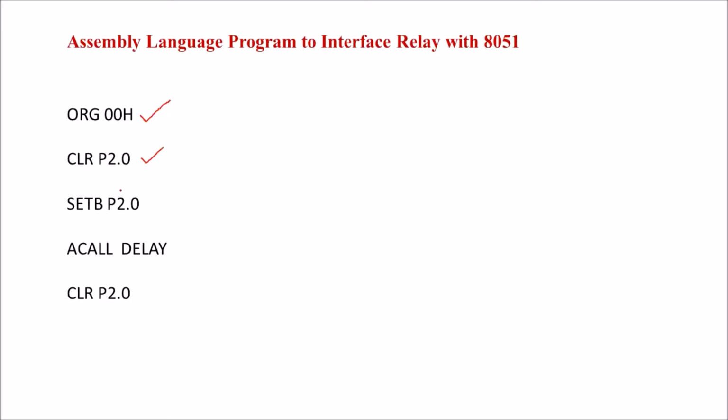Now whenever we want to turn this bulb on, we'll send logic 1 to the transistor. So the transistor enters the saturation region, current will flow through the relay coil and the relay will close the switch. So the bulb will be connected to the 230 volt supply and it will turn on.